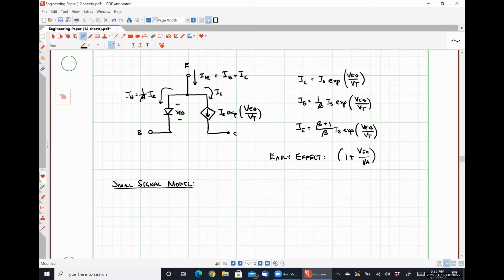Yes, so we worked a whole lot of problems that would be considered a common emitter amplifier topology with the NPN transistors. There are common collector topologies where the collector isn't grounded per se, but it's at an AC ground, and we'll talk about that later on today. But in the most simplistic amplifier circuits that we'll be dealing with of the PNP variety, typically the collector is the one that's at ground.